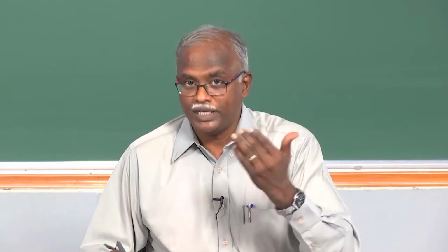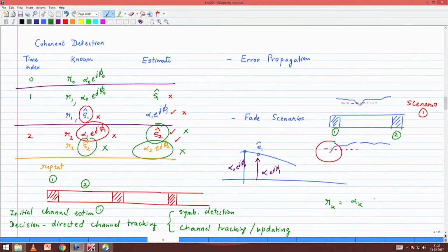I know what has been transmitted, so therefore why am I not able to estimate the channel correctly? So here is Rk equal to alpha k Sk plus eta k, correct? That's the equation. During training, I'm going to put a tick on what is known. This is known, this is known. What is not known? This is not known, that's a random quantity.